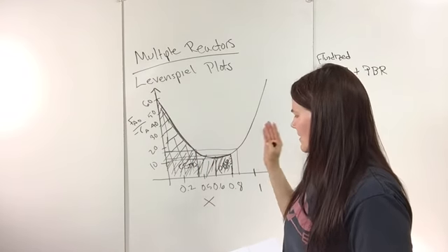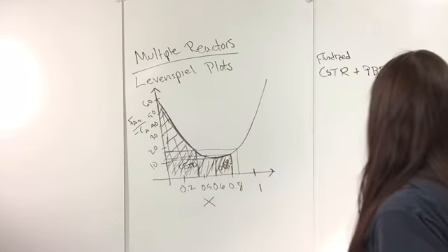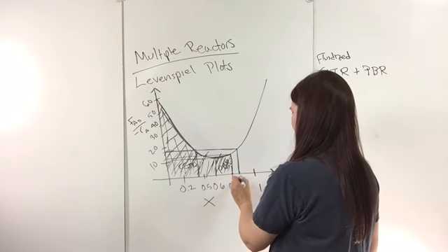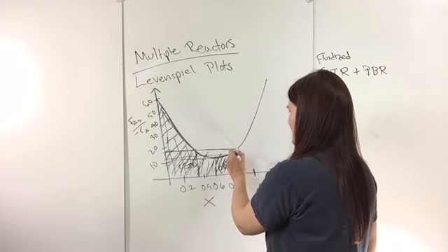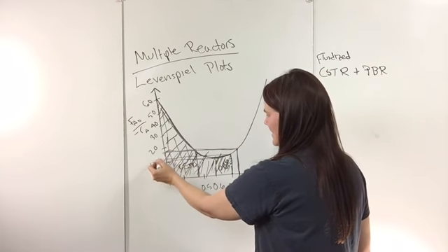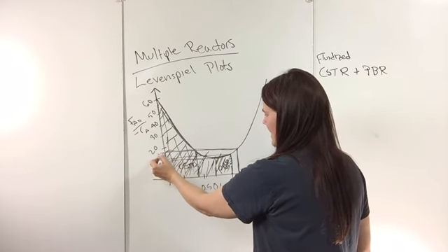The volume, or in this case the weight of the catalyst, for the PBR is the area under the curve, and for the CSTR it's just this area of wherever you are on the plot. So from here, this would probably be like 90% right here. So you go up to the curve, go over, and then it's just whatever's here. So say that's 18, so 18 times 0.9.